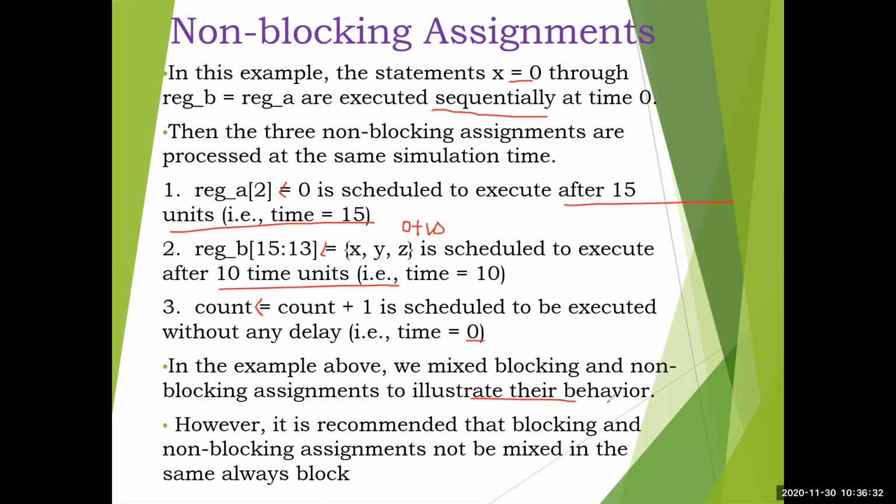We have just mixed them to understand or differentiate their behavior. However, it is recommended that blocking and non-blocking assignments not be mixed in the same always block. So this is the recommendation. You should not do it; just for illustration I have used it here, but it is highly recommended that you should not write blocking and non-blocking assignments in a single always block.